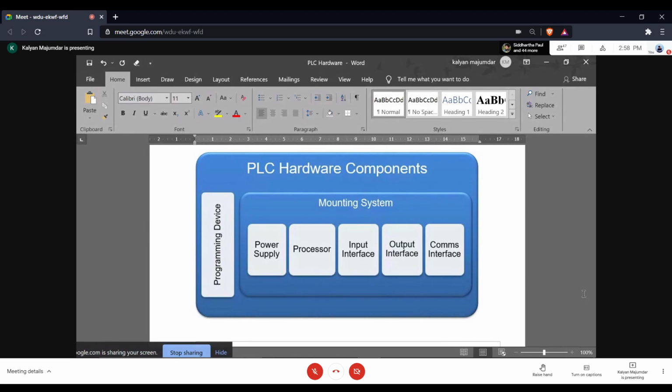But as of today, all modern PLCs use Ethernet connectivity. Your laptop or your desktop computer has a standard RJ45 for Ethernet connections, and your PLC also has an RJ45 for Ethernet connectivity. So you can simply take a cable, Cat5, Cat6, whatever, and connect the two Ethernet ports, one on your laptop, the other one on your PLC, and that way you can establish a connection between your laptop and your PLC, your courses environment and PLC. You can transfer your program,